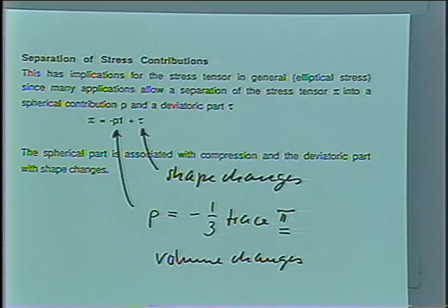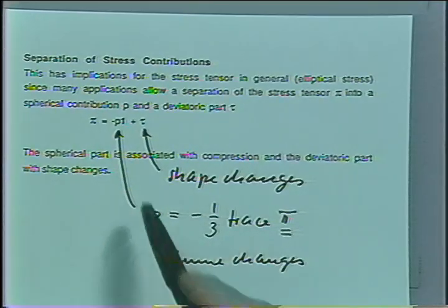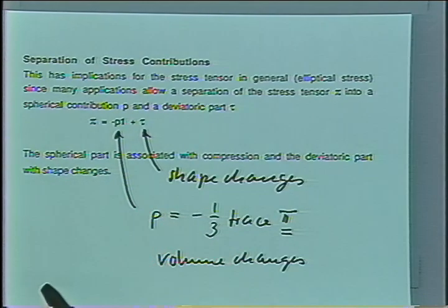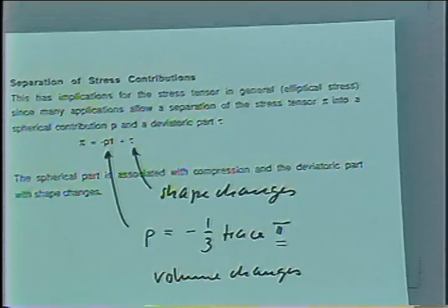And that eliminates really a whole area of physics. The volume changes are described in thermodynamics. Volume as a function of pressure and temperature. And if we say we have constant volume, we just neglect all thermodynamics, which is probably not appreciated by people working in thermodynamics. But it's a tremendous simplification. Just allows us to get solutions in fluid mechanics problems, and we have to be aware of that simplification.